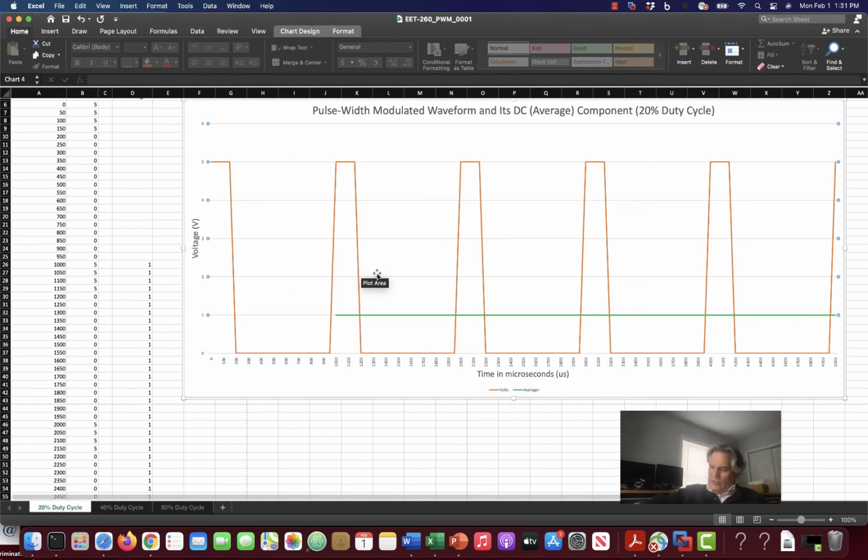You can imagine a device like that. You could put 5 amps through it and drive a pretty powerful motor with 5 amps, and the device wouldn't even need a heatsink. So that's another reason. In fact, some audio amplifiers now, instead of trying to drive a continuous sinusoidal value between a minimum and maximum, they put out a series of pulses of various widths, so that this average voltage will track what the sinusoidal waveform would have been, or whatever music waveform you have.